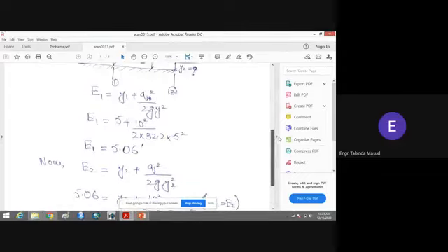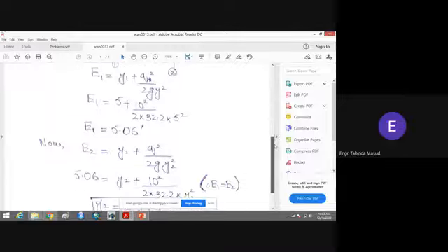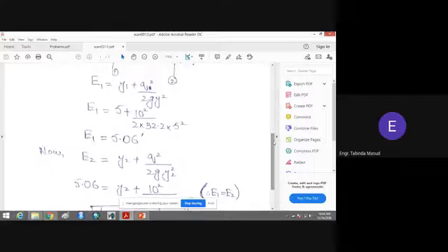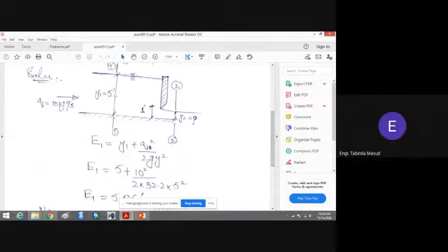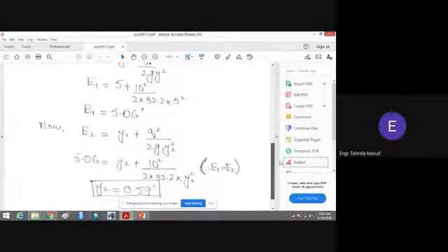There is also a hint: if you want to solve it by trial and error procedure, you can see that in the subcritical state, the depth of the flow is 5 feet, and now we are going to find the depth of the flow in the supercritical state as shown in the figure. So the depth of the flow at the upstream is 5 feet, and you will put different values of y2 that should be less than 5.